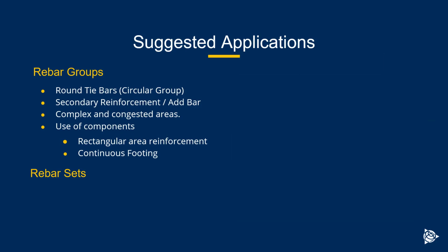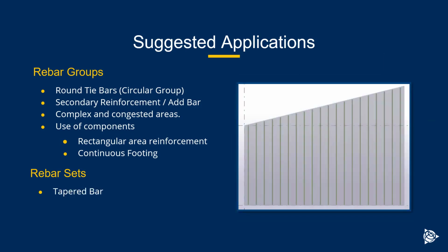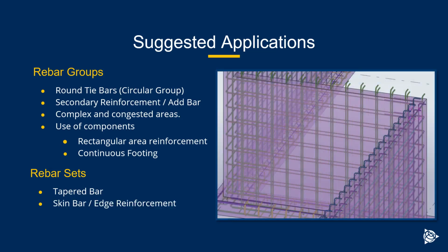Now, for rebar sets, I think that tapered bar, it really excels for that. You don't have to explode the group. It's ready to go, and it's easily more updatable if you get changes sent to you. In that same vein, conversely with rebar groups, I think doing your skin bar or your edge reinforcement or any sort of just contouring to the surface geometry of your concrete, whether it's parts or pours, I think that's where rebar sets really excel. And that kind of flows into generic or basic concrete reinforcement. I think the sets really kind of expedite some of that placement.